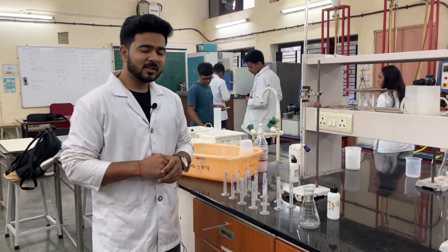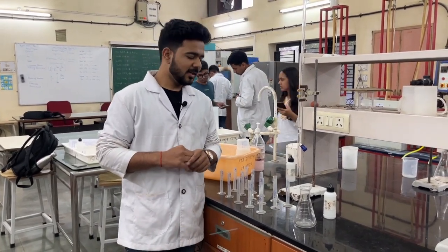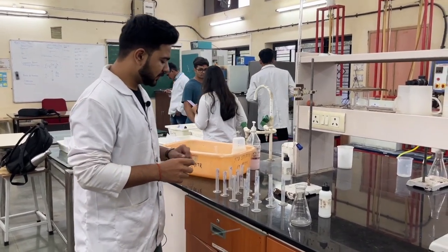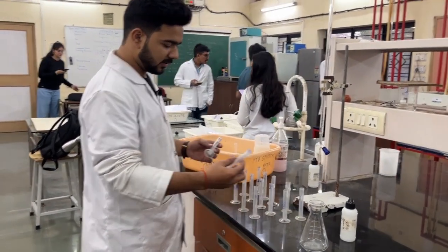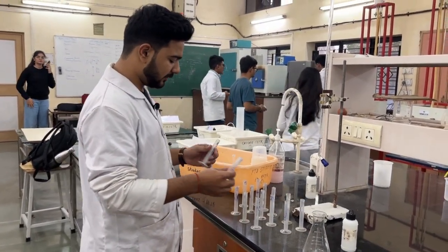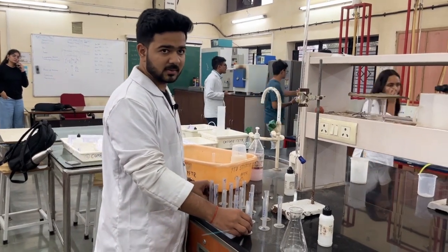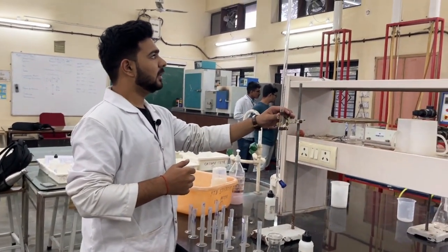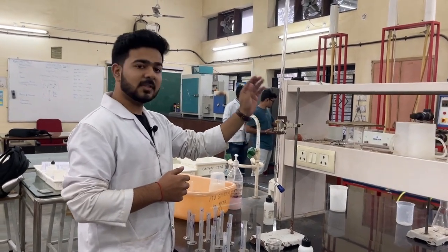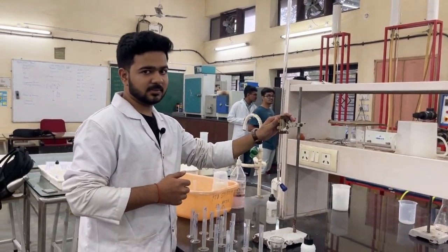While waiting for the reactor to attain the steady state, we will set up our tubes in which we will take our 15 samples. Here are 15 cylindrical vessels of 10 ml each. After that, we will fill our burette with NaOH against which we will titrate our further readings.